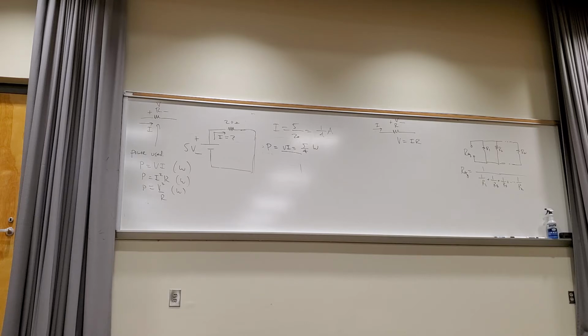How much power does a hairdryer burn up? Yeah, in the thousands of watts. You can go for about 1,000 to 1,500 watts is typical, isn't it? Yeah. I think it's typical. I suppose you can get them as low as you want, but that's a typical range, all right? The wall voltage has 117 volts RMS, call it 120, right? So what would that make the current if you had 1,000 watts?